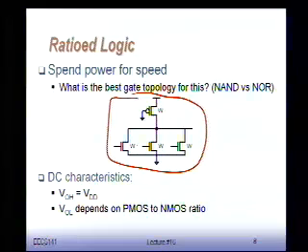Making the PMOS the same size as the NMOS works, because remember, the PMOS is always a weaker device. As a result, the resistance of the PMOS in this case is going to be somewhat larger, about a factor of 2, than the resistance of the NMOS, because I make them the same size. And it turns out that it's a fairly decent ratio in terms of both performance and noise margin characteristics. Now, here's an interesting question, right?